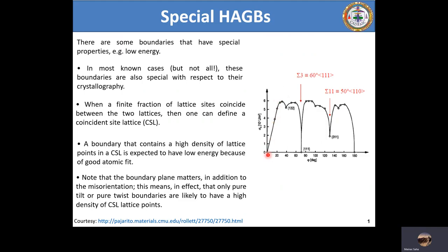In a real microstructure, we see these low angle boundaries in the form of subgrain boundaries that I also showed you in one of the previous sessions. If we consider the CSL model, we will consider these low angle boundaries, not all these local minima CSL boundaries. In the CSL model, these low angle boundaries will be considered as the sigma 1 boundary. Sigma 1 boundary means each and every lattice plane between the two adjoining grains will be in perfect coincidence with each other, or in other words, continuous across the grain boundary plane, isn't it?